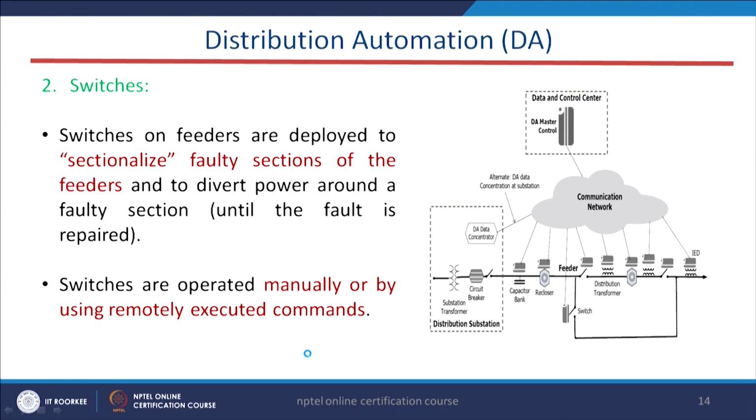Maybe a small processor is present inside it, and that processor will receive the signal and do the desired work. That is where the electronic switches, static switches, come in, and those switches basically help in sectionalizing faulty sections of the feeders. Let us say in some part of the feeder we have a fault. What will happen? These switches will help in isolating or sectionalizing that particular faulty section from the healthy section.